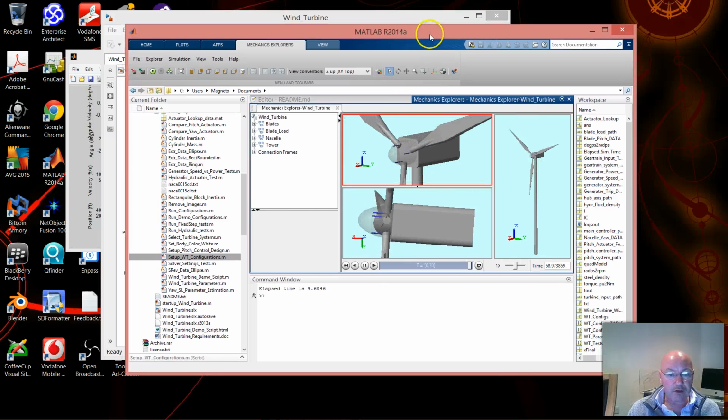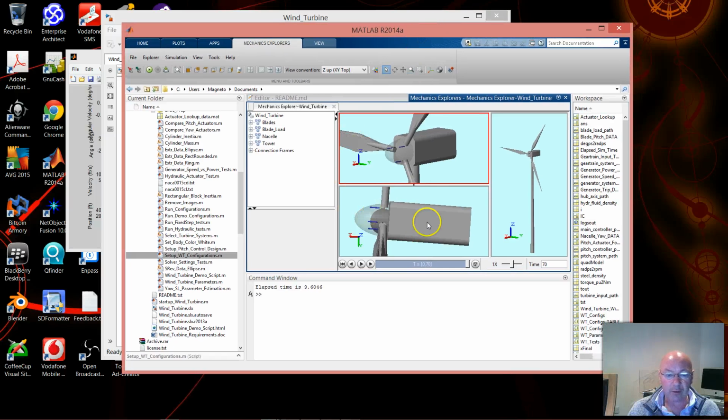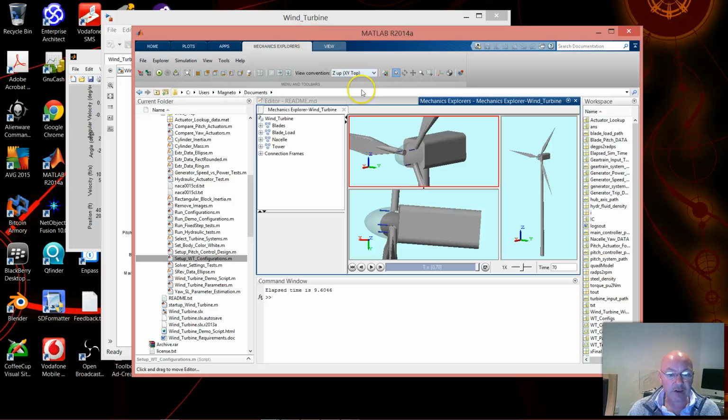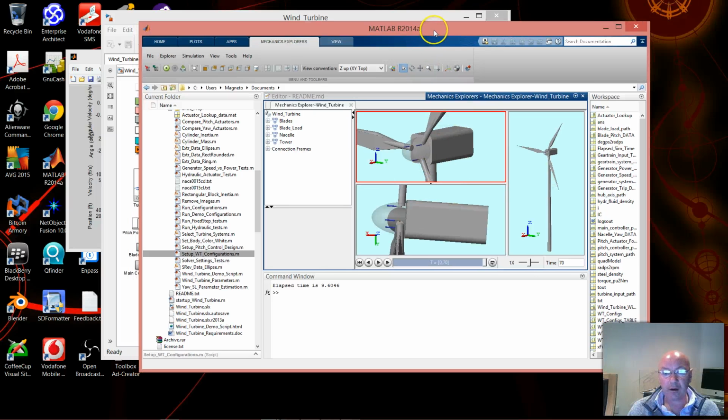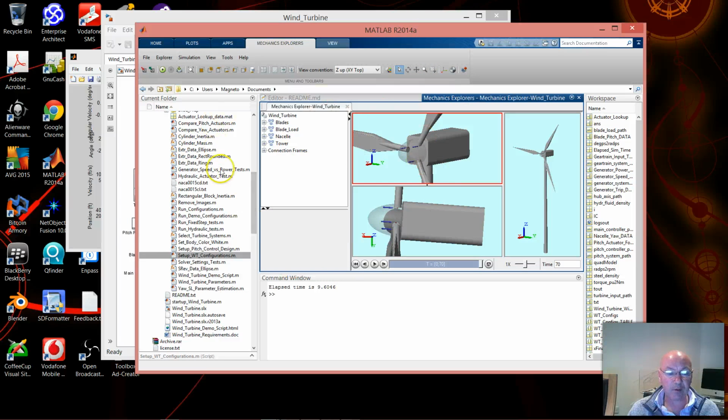The third model I'm going to show you is how these things actually get put into hardware. Now, all of these models potentially can be put into hardware. They just need to be either designed in the first place for code generation, which means you're restricted to a certain set of elements, as some elements you can't use, or if you have an existing model like this, you can go back through and replace all the elements which may not be compatible with code generation.